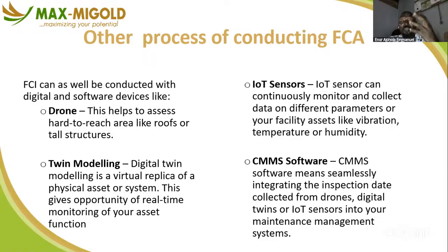Or when the building is gaining in terms of humidity, that is going to be weakening the strength of the building envelope. Then vibration, when you are getting a lot of vibration from the building, where is the vibration coming from? Because if the vibration is huge, it can start causing what we call structural differential settlement of that entire building.